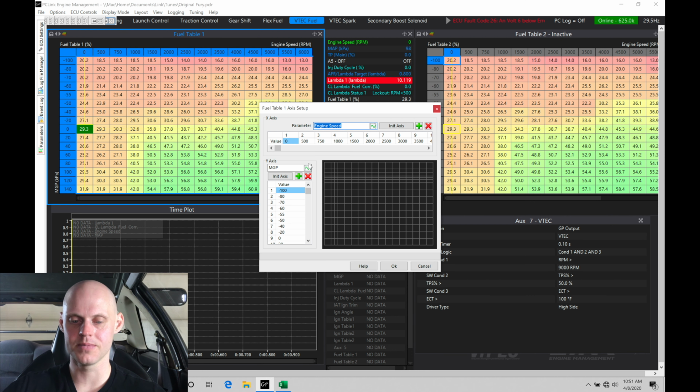Let's click X here. And in the values, I don't need to have my breakpoints going, you see 750, 1,000, 1,500, 2,000. Let's get rid of 750. Let's move up here and get rid of 8,000. We're only going to go up to about 7,500. So low cam, we don't want VTEC going in and not operating at something like 7,500. That's hard on the rockers. It actually can break our rockers. I usually try to have my VTEC coming on way before 7,000. So table will go out to 7,500.